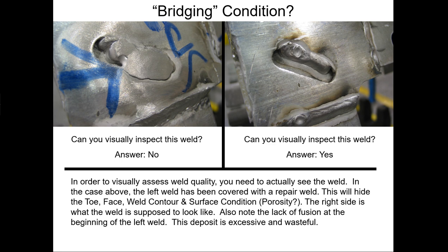When we go to the plants and they want to do a destruct test, that is loaded onto a machine and they beat this engine cradle, this component, to death to find out where its weakness is, they look for the ones that are reprocessed because they've been welded again. And they know that they're among the worst, especially right beside the repair, because often the repairs are too significant. They put too much weld on, too much where they don't need it.